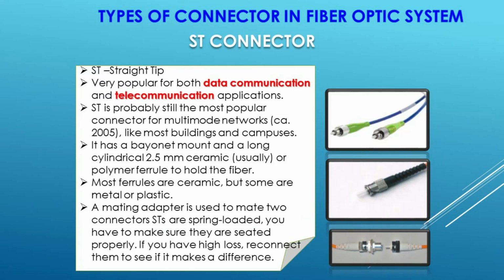ST connector. ST, straight tip. Very popular for both data communication and telecommunication applications. ST is probably still the most popular connector for multi-mode networks, circa 2005, like most buildings and campuses. It has a bayonet mount and a long cylindrical 2.5mm ceramic, usually, or polymer ferrule to hold the fiber. Most ferrules are ceramic, but some are metal or plastic.